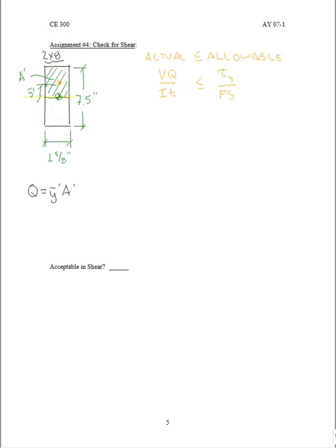That is on our diagram. So our y bar prime in this case is 1/2 of 3.75, or half of the height, inches. And our outward area is 1 5/8 inches times 3.75 inches, for a total first moment of the outward area of 11.42 inches cubed.